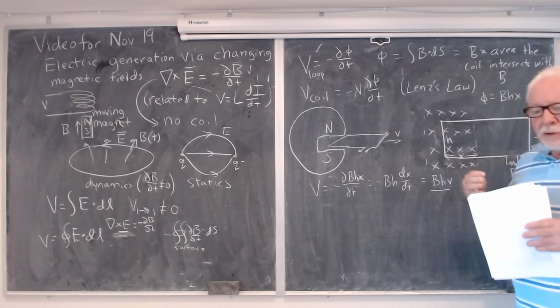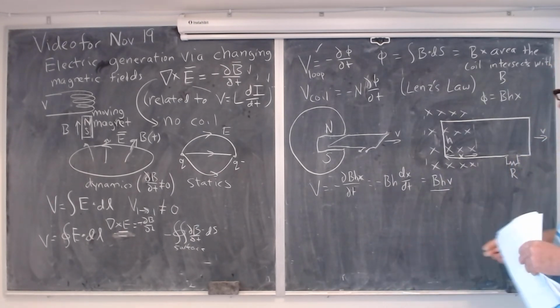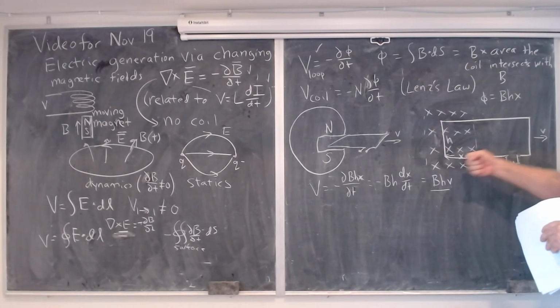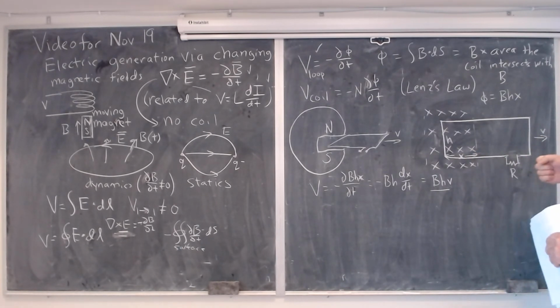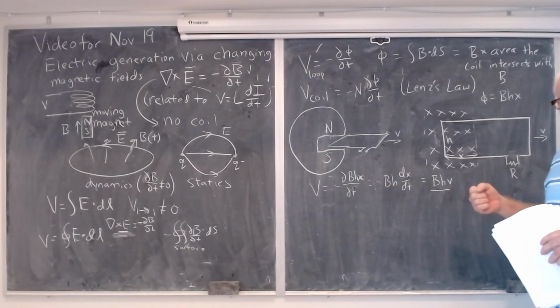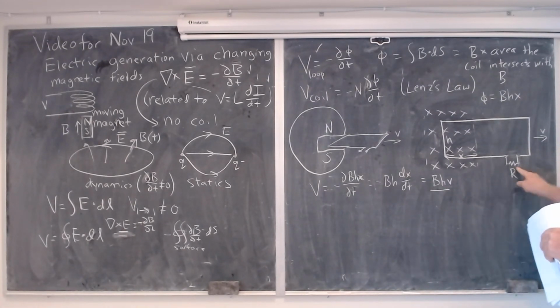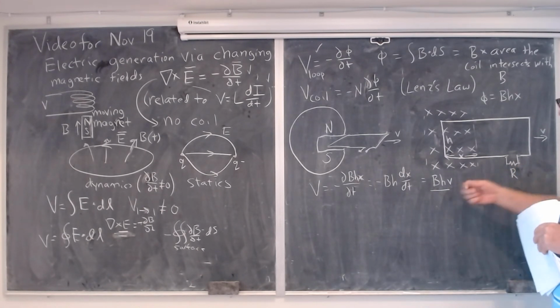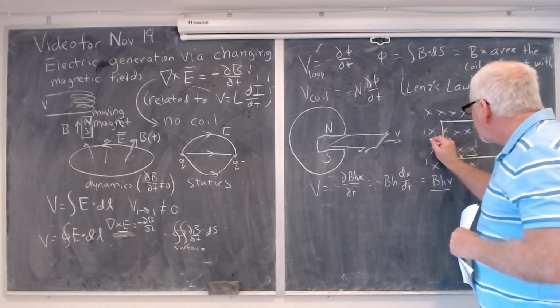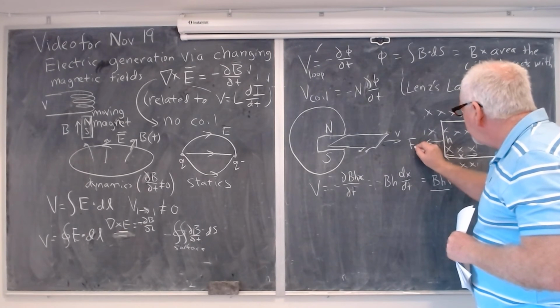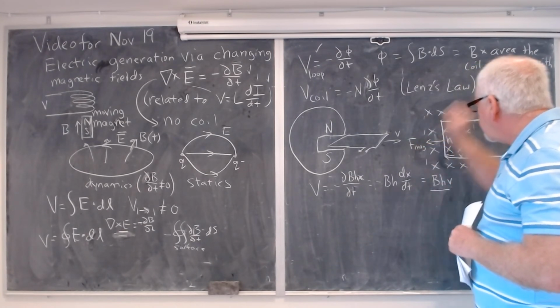Now, just logically, if I'm pulling this coil, then it should resist me pulling it. Because if I put a resistor there, I'm producing electric power, I'm dumping power in the resistor. And so pulling that coil should resist me. It means there should be a force on the coil due to the magnetic field in the opposite direction.